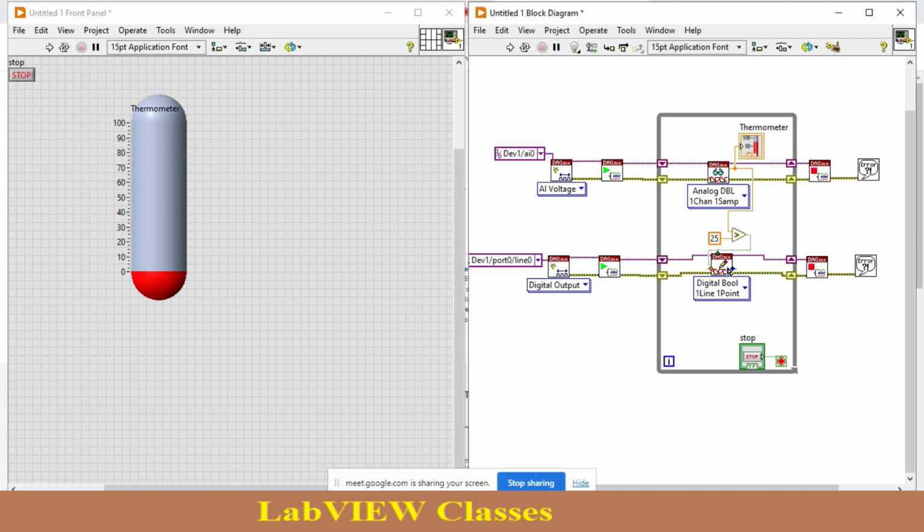On the other side, we connect our load. Not an AC in this case, because the capability of this relay is not for AC. It will run any fan or light. For higher capability, we replace this relay with a higher-rated one.